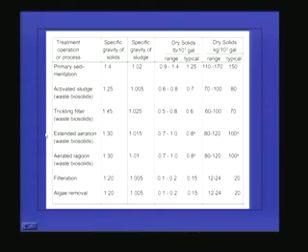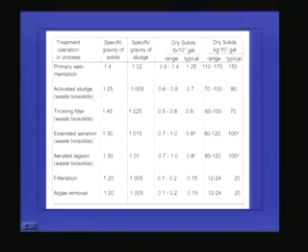This table gives us the basic properties of the sludge we get from various treatment processes. If you take the primary sedimentation tank, the specific gravity of the solids is in the range of 1.4, but the specific gravity of the sludge is only 1.02. Though the solids have high specific gravity, we know that the sludge contains a lot of water, around 95 to 96% water, and the solids are only 2 to 4%. So the net specific gravity of the sludge is very low, almost equal to water, 1.02.